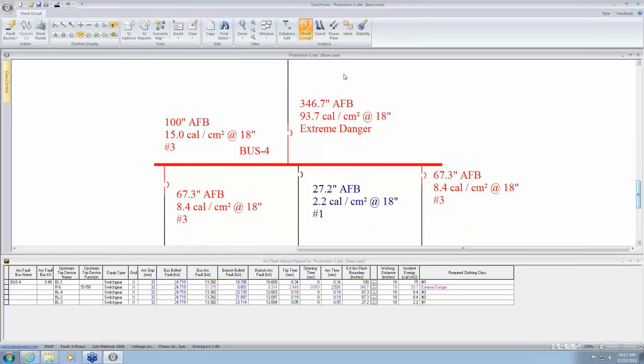That is, a lot higher than 2 seconds. And IEEE 1584 standard, as well as NFPA 70E, the 2012 edition, says that if your calculated trip time is higher than 2 seconds, it's okay for you to assume a 2-second maximum time.